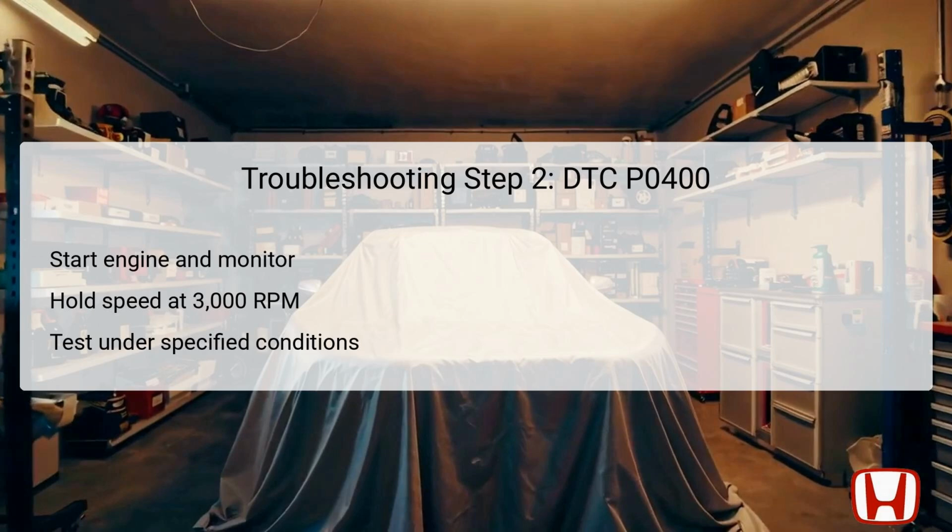The next step in the troubleshooting process involves starting the engine and holding it at an engine speed of 3,000 RPM without load. This means that for automatic transmissions, AT, the gear should be in park or neutral, while for manual transmissions, MT, it should be in neutral. The goal is to maintain this RPM until the radiator fan activates, and then let the engine idle.